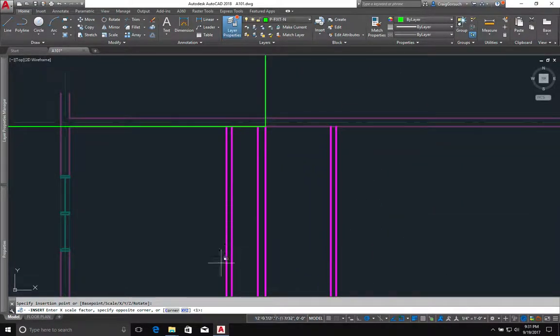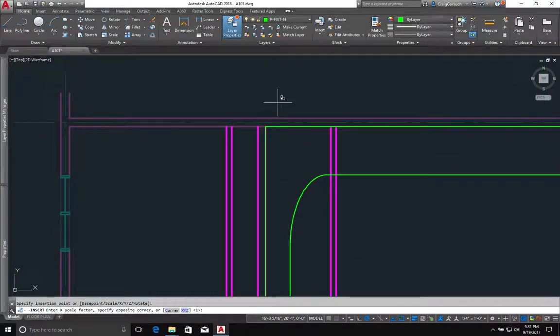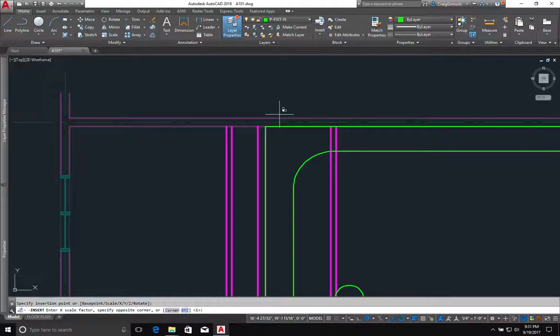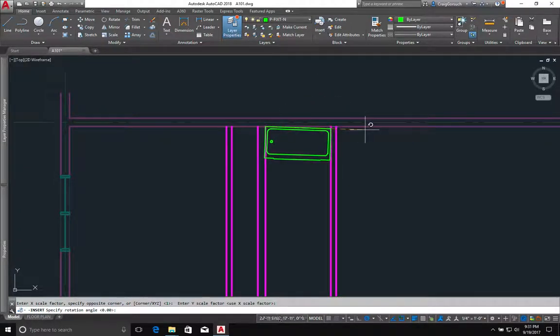At this point, AutoCAD is asking right down here, what's the scale factor? Most of these blocks, with few exceptions, you use at a scale factor of 1, so we can accept the default. We want the Y scale factor and the Z and the X scale factor to be the same, so we'll accept the default again. And now you can either left click on this axis, or snap on a point to establish an origin. Right now its default rotation angle is 0, and my cursor is at 0 degrees, so I can push return because that's the default, or I can actually key in 90 degrees if I wanted my bathtub going that way. I'll just left click right here.